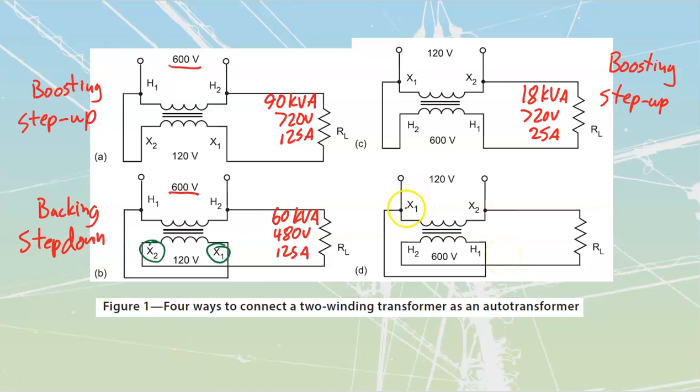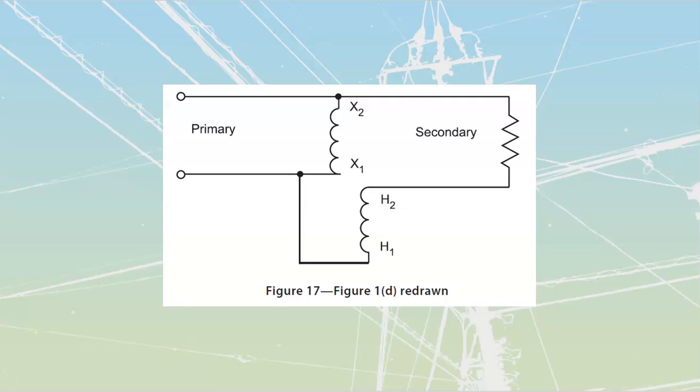The last connection that we have over here, we see we're connecting a 1 to another 1 inside of here, or a same polarity to a same polarity. And they start by making a simplified autotransformer drawing of that application over here. Once again, it shows this drawing with a connection over here and this one pushing back down there. It is sometimes easier to visualize it if they would just draw the other one kind of pushing back in like that, so that you then see the way that second winding is kind of pushing away or cutting away from my primary winding.